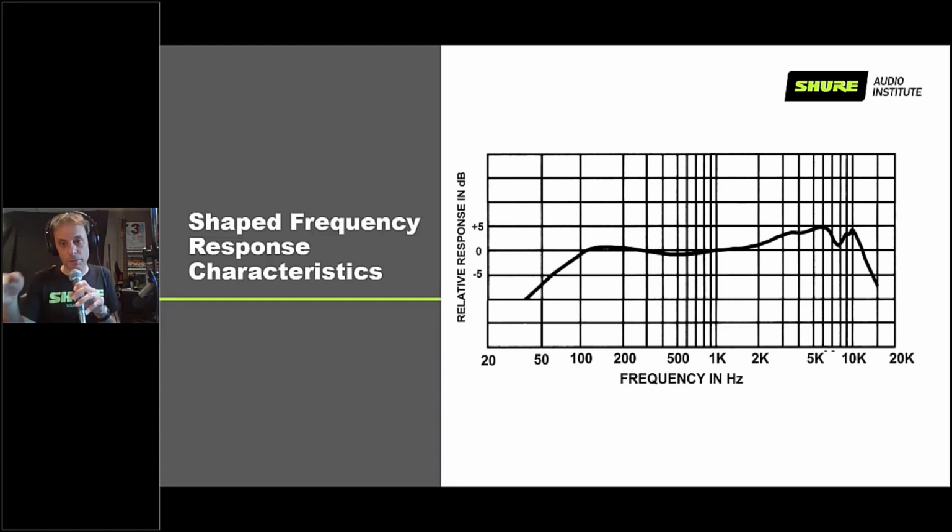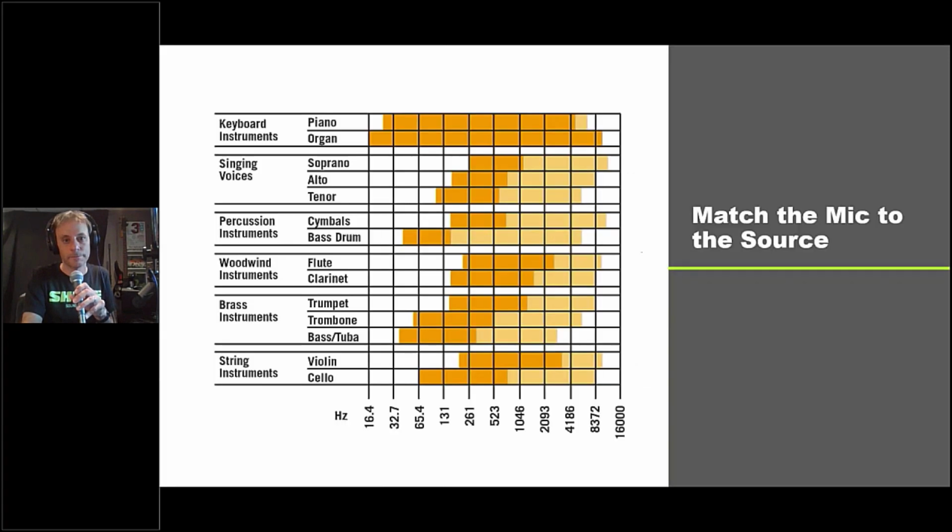And then again, there's a dip above 10K, which is also good because frequencies above 10,000 hertz, if you do reproduce those, they might sound a little bit more natural, a little bit more real, but they offer nothing in terms of intelligibility. So in terms of just being able to understand or get a real full character of what's happening, you don't necessarily need those. But for studio, for recording applications, for higher end things, it might be useful to have those there.